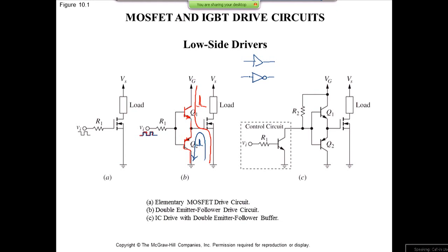And remember that the controller needs its own power supply. Now this power supply should be able to handle a high impulse of current. So for that reason, if this is a chip over here, you usually add an extra cap over here as well, and this cap is actually providing that extra amount of current. It is a combination of an electrolytic cap and a low internal resistance ceramic or film cap.